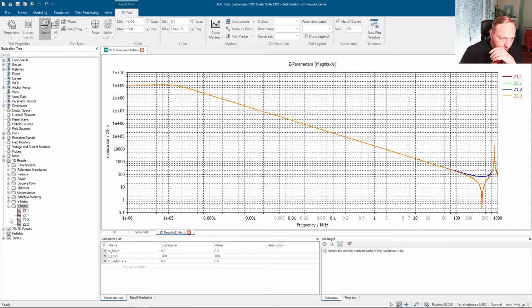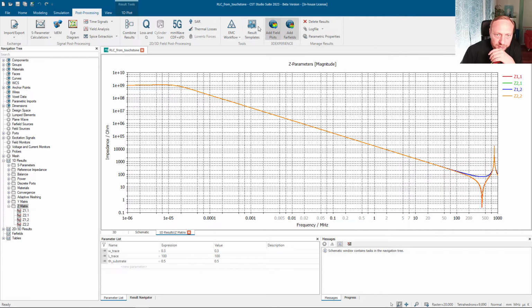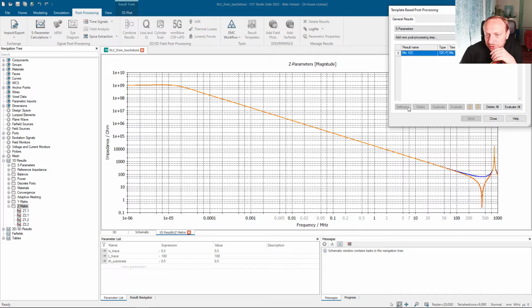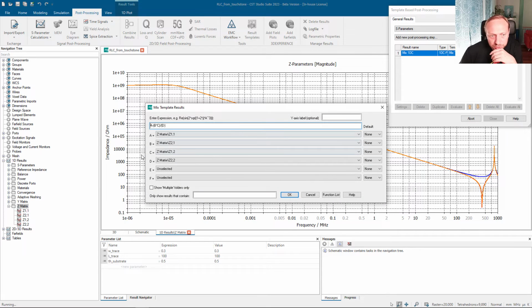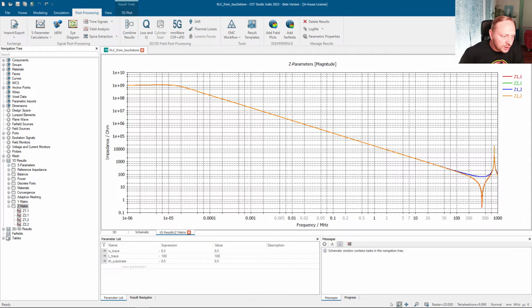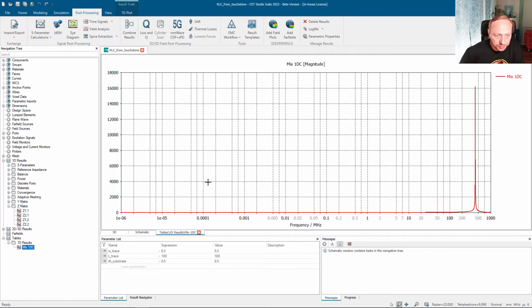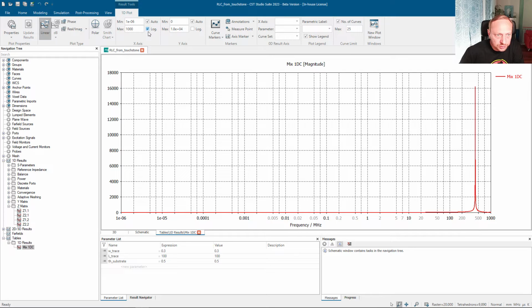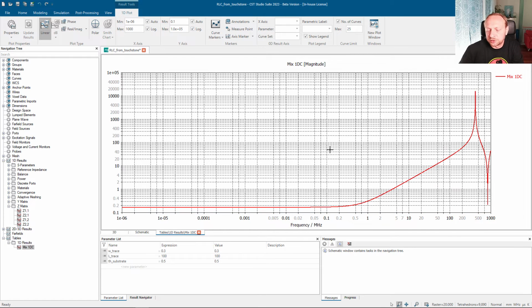We can do this. So I can go into the post-processing steps and type in these equations. And if I do this, you see the D, and in the denominator, the termination impedance or the load impedance is set to 0. And if I do this, I get the loop impedance. So this is the loop impedance, which shows me, let's plot it double logarithmic, of course, up to here, it behaves purely resistive.